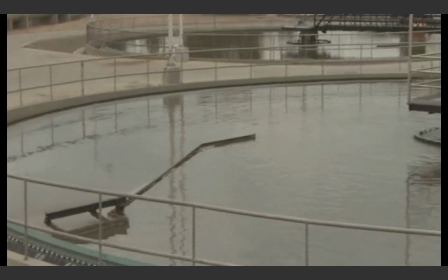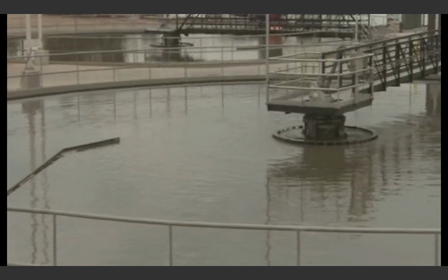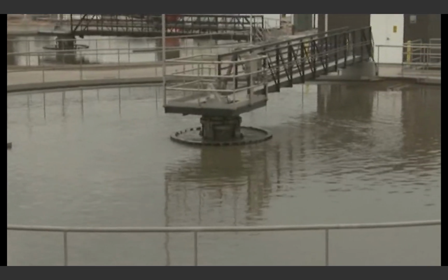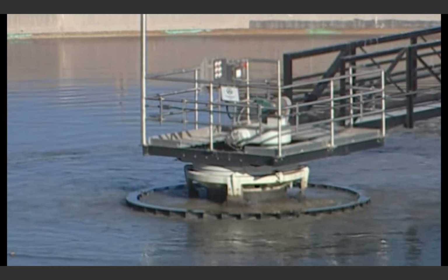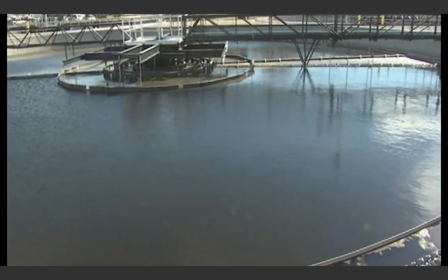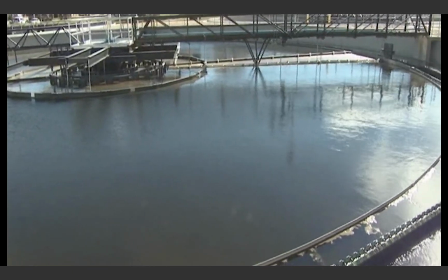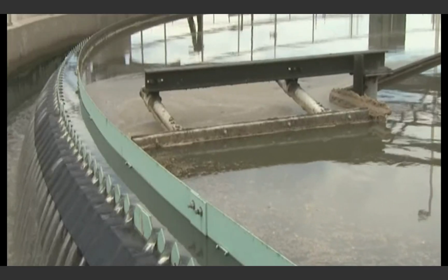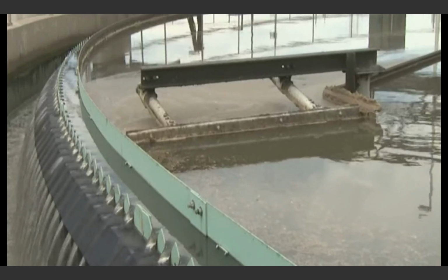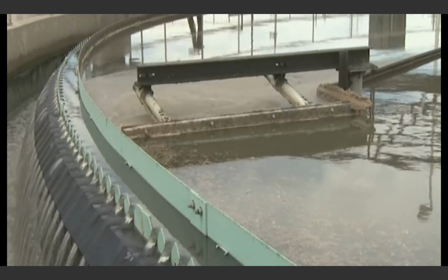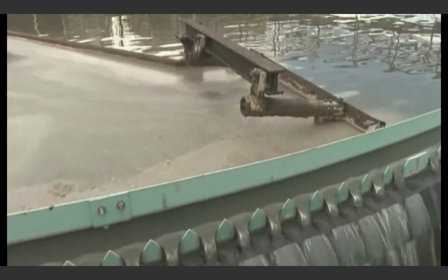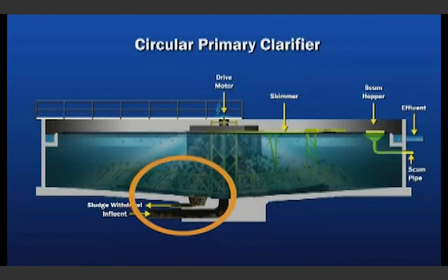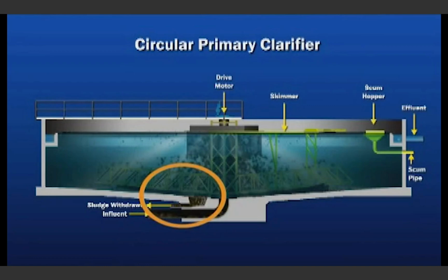Most sedimentation basins have 4 zones. The influent or inlet zone decreases the velocity of the incoming water and distributes the flow evenly across the basin. The settling zone provides the calm area necessary for the suspended material to settle. The effluent zone provides a smooth transition from the settling zone to the effluent flow area. It's important that currents don't stir up any settled solids and carry them into this area. The final zone is the sludge zone, where settled solids are separated from other particles in the settling zone.